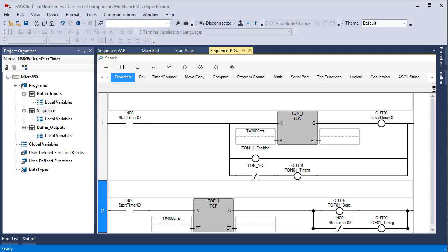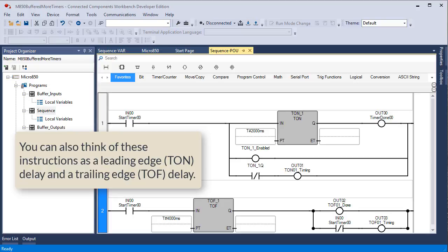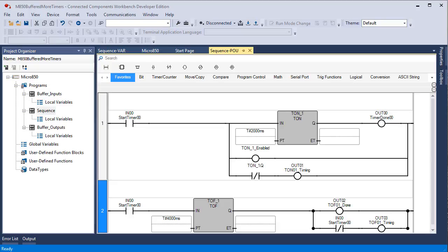That other event could be anything, but a TON is an on-delay timer. An off-delay timer, you have an event, but nothing happens. But when that event goes away, in other words, when that first event goes off, then there's a time delay before the other event goes off. So on-delay, off-delay. The enabled bits that we created, which are available with RSLogix's timer data types, that's just inherent, intrinsic in the data type.